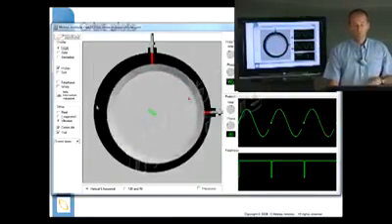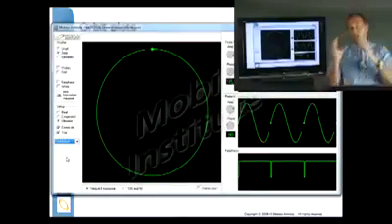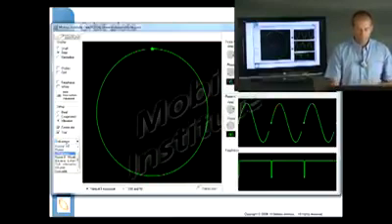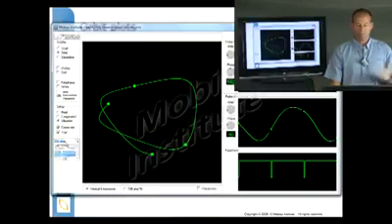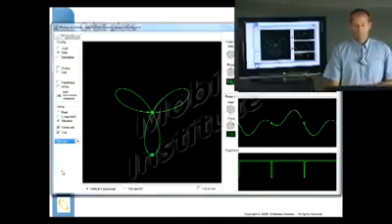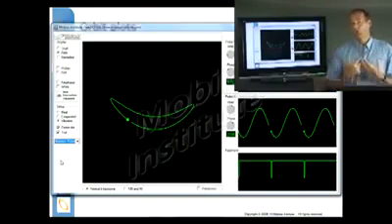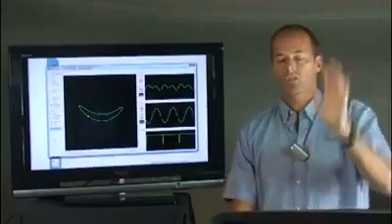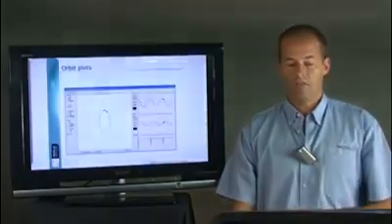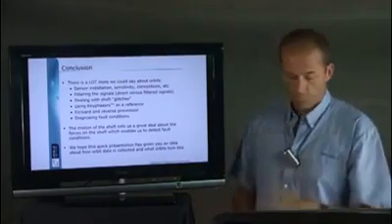And we can go through with lots of different demonstrations. If there was unbalance, there might be a lot more motion. If there were rubs or instabilities and oil whirl and all sorts of things, you get all kinds of interesting looking shapes. That's just something interesting I came up with. Just different sorts of shapes, depending on the forces on the shaft. There's a lot more we could go into with this, but I hope you get the idea of how those orbit plots work.